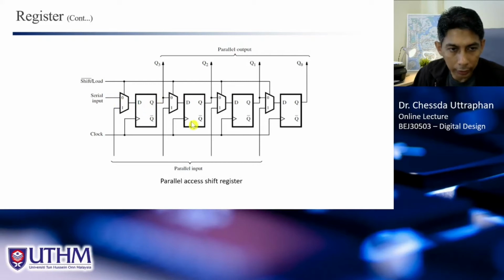And for the second flip-flop, instead of from the parallel data here, it is from the first flip-flop, going to the second flip-flop here. And the same for the third flip-flop, where the input is coming from the second flip-flop here, because this one is 0.